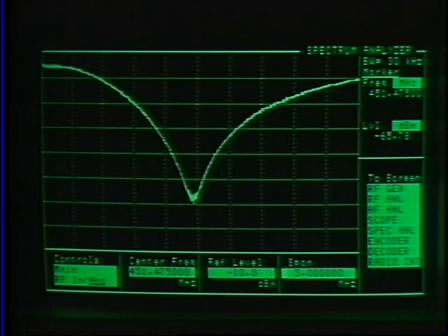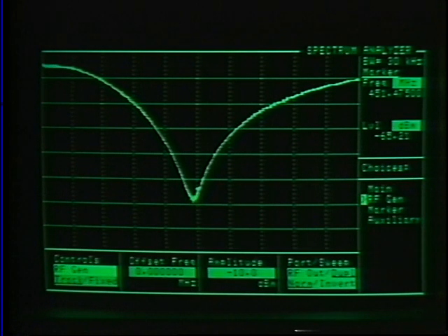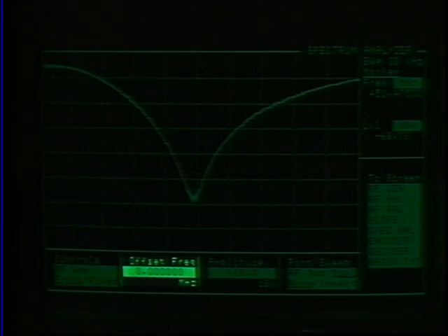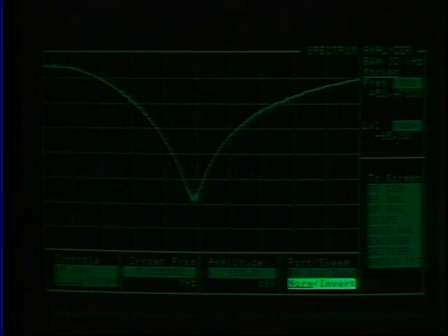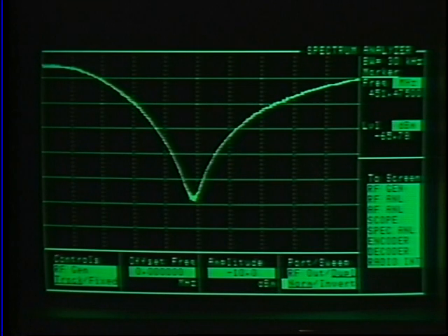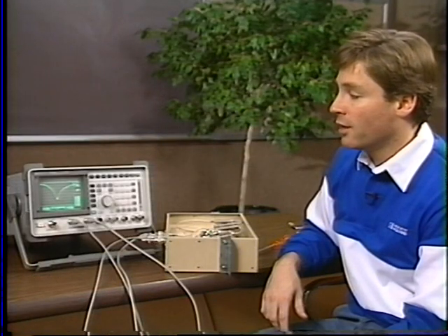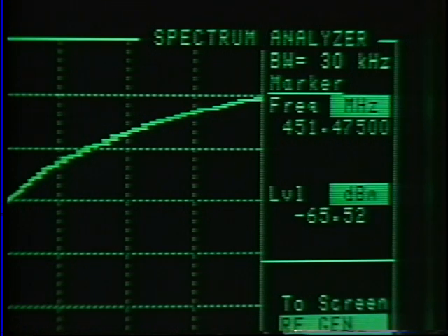duplexers. Other features available with the spectrum analyzer and tracking generator include a full offset capability, where the tracking generator and spectrum analyzer can be offset in frequency for doing IF to RF conversions or crossband repeaters, as well as normal and inverted sweep, where the spectrum analyzer and tracking generator track in different directions in frequency, one up and one down, for characterizing such things as superheterodyne receivers. In addition, using the tracking generator, you still have the same marker capabilities as with the spectrum analyzer, with readouts of frequency and level for measuring the depth of a notch and the center frequency of the notch.